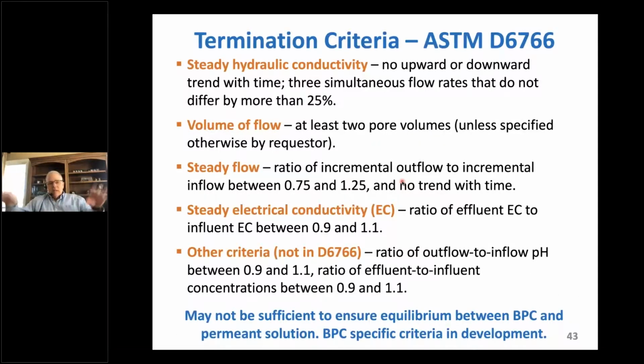So we're running the test. We've got it prehydrated, we got the leachate, we've got it all set up, we got the stress criteria, we're running the test. How long do we have to run it for? What are the termination criteria? We'll take a few more minutes to look at these. Well, these are spelled out in D6766.